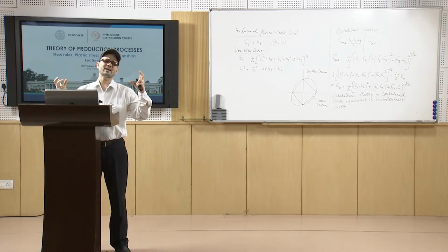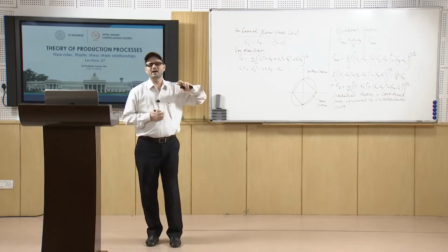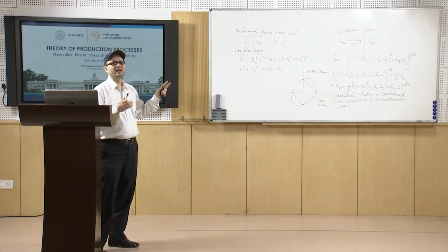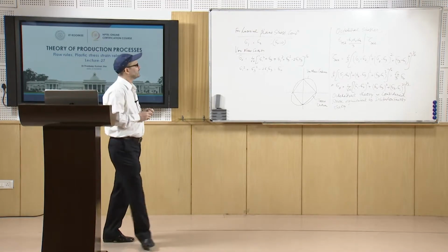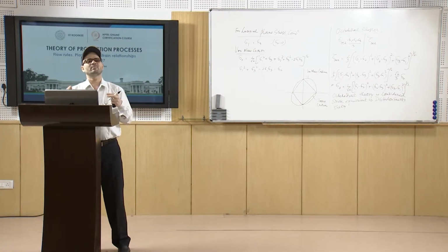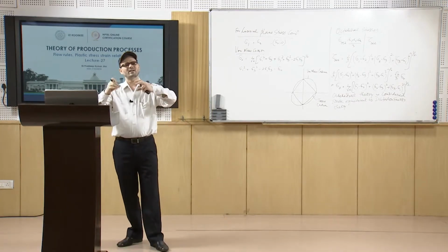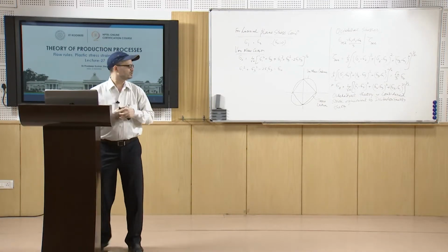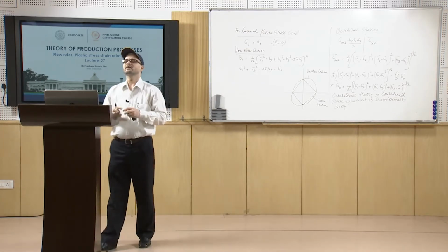Now, if you talk about the octahedral shear strains, you again have the mean strain. So, linear strain will be (epsilon 1 plus epsilon 2 plus epsilon 3) by 3, and then octahedral shear strain is further defined as 2 by 3 of [(epsilon 1 minus epsilon 2) square plus (epsilon 2 minus epsilon 3) square plus (epsilon 3 minus epsilon 1) square] raised to the power half. So, this way we define the octahedral shear stress and shear strain.